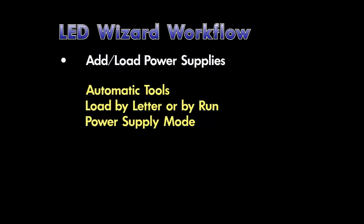In summary of adding and loading power supplies, we have automatic tools for adding 1 power supply per letter, 1 power supply for all letters, and optimal power supplies. We also have an option to load power supplies 1 letter at a time or by 1 run at a time. And then we also have the power supply mode, which is used to add multiple power supplies to 1 cabinet or 1 letter.